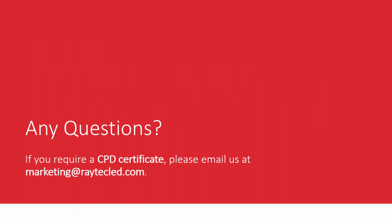Thank you. What is the minimum IP rating for ATEX equipment for Zone 1? So any ATEX equipment has to have an IP rating of IP54 as a minimum. For all Raytec products, all of our products are generally done to IP66 and IP67 to make sure that they're rugged enough for any situation they find themselves in.